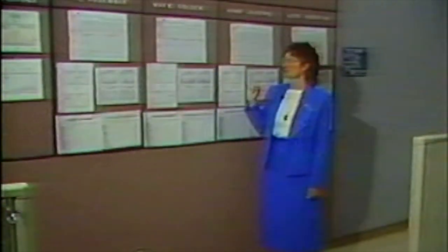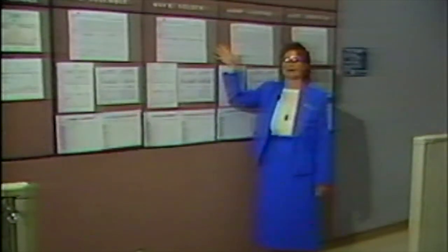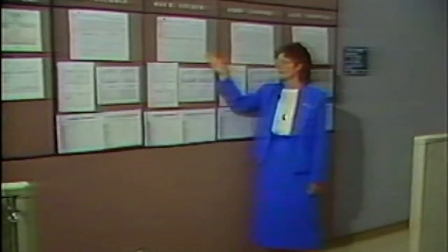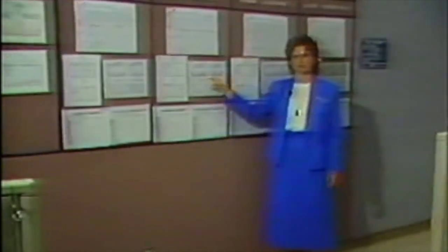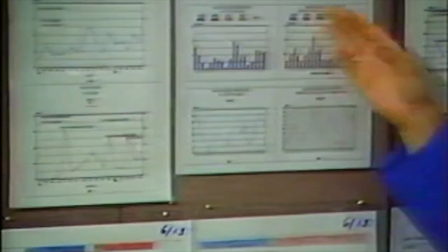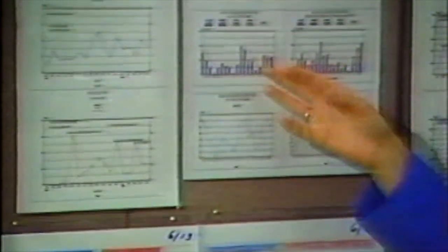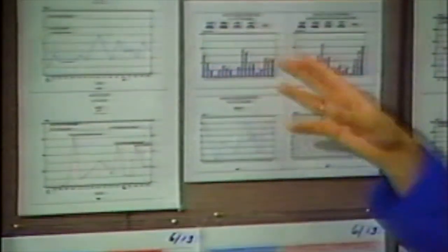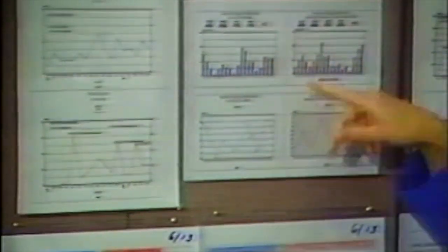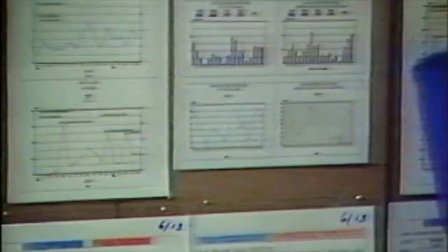In particular, this is the wave solder process, and you can see here that we have short-term feedback, actually daily feedback on this X/R chart. We move down here and we see Pareto charts, so we can look at long-term trends over a number of weeks from week 5 to week 23. We're also able to look at defects found internal to the process and defects found at the customer in the next process in the flow is their customer. The Pareto charts here are quantity based, and then we also have a parts per million level of X/R chart.